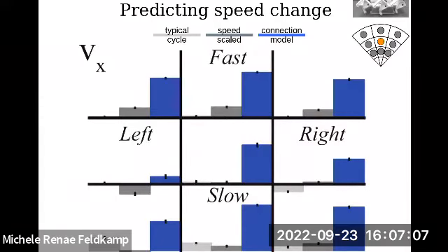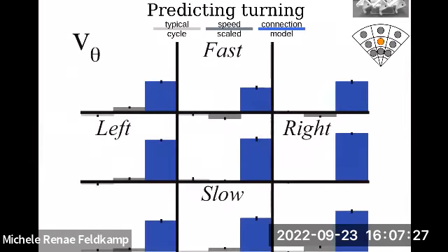So let's see if we can predict how fast the robot moves. The other model is doing pretty poorly. We're at, by the way, this is just 100%. So that's why the numbers aren't in here. So this is 70, 80% prediction. So pretty good prediction for speed, pretty good prediction for turning, all on training data of the robots walking at the intermediate arc. So we had those 3 bundles of lines. That's taking data only from the middle bundle and extrapolating to the other bundles. Okay. So we actually can learn a lot about this robot's physics using this very, very naive method.